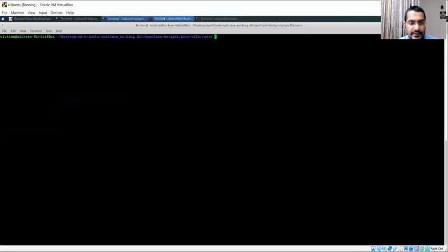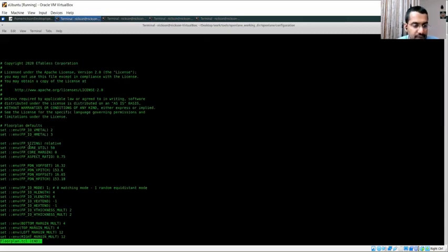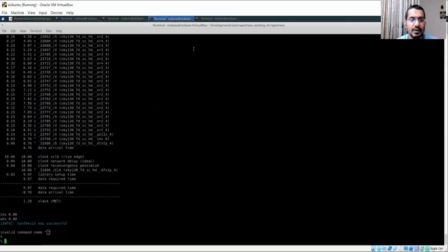So let's see, here core utilization is 50, vertical metal is 2 plus 1, that is 3, horizontal metal is 3 plus 1, that is 4. Now with these settings, let's see what the run floorplan does.